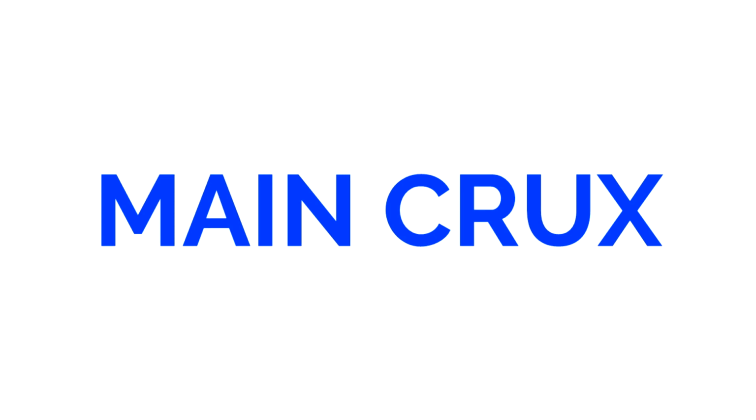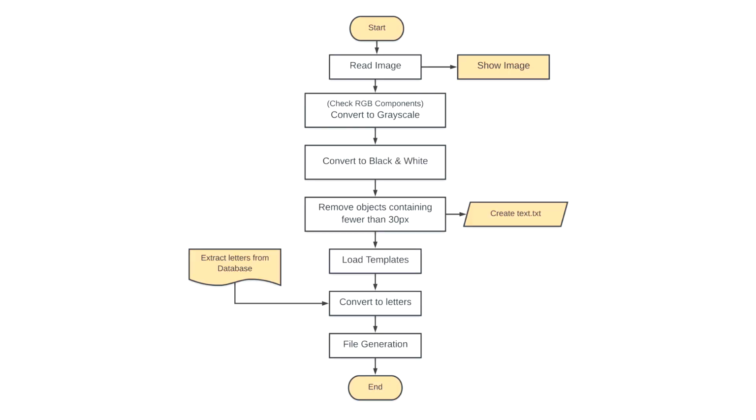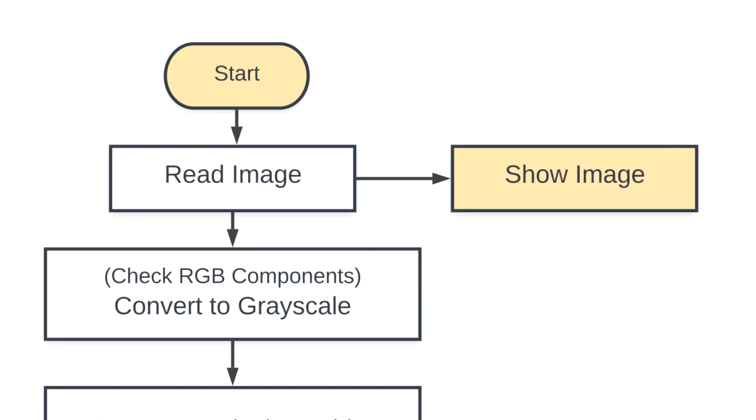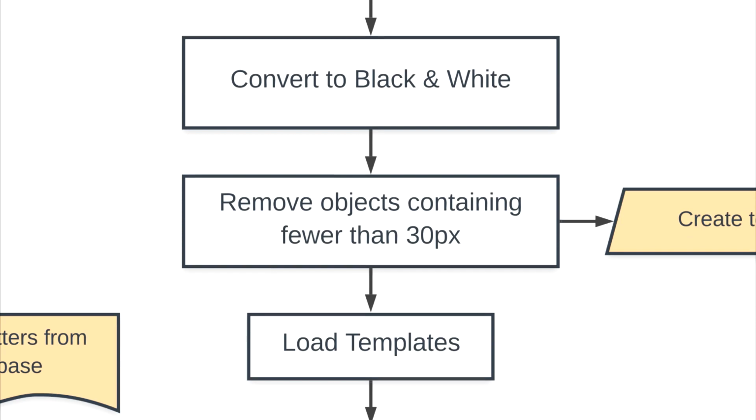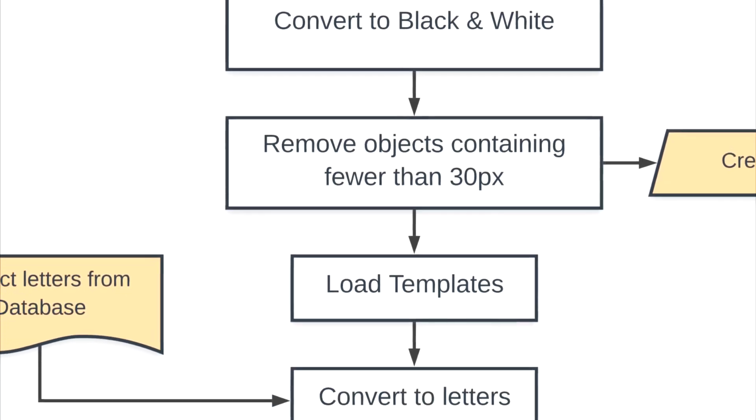The main crux of the project is three necessary processes. The flowchart for the same is as you can see. First, a color image captured from the camera module, or a pre-stored version of the image, is converted to grayscale levels by using a black and white conversion method. Then this grayscale image undergoes thresholding such that pixels having a value less than 0.44, in our case, are removed. More often, such pixels are redundant and have no major effects on the image, but the data to be processed is reduced and image artifacts such as dots and graininess are reduced.